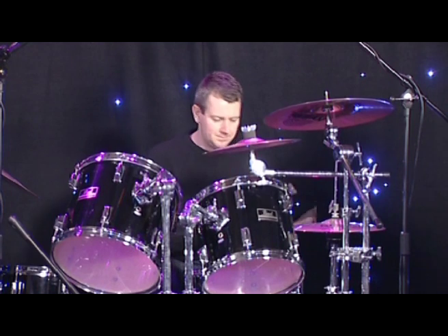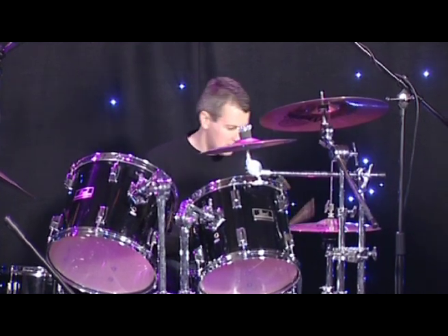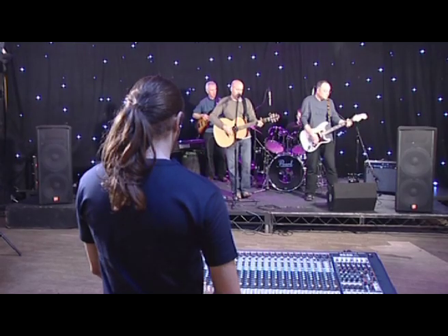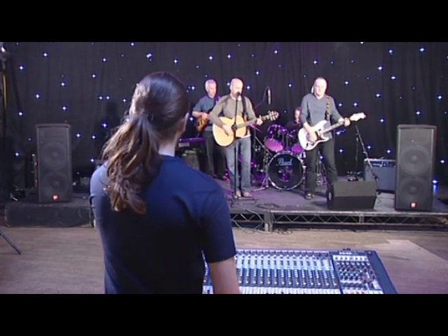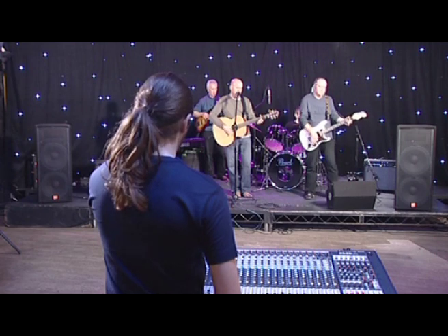Don't put vocal microphones directly in front of the drum kit or a guitar amplifier. Make sure nothing gets in between the loudspeakers and the audience. Aim them down towards the listeners, don't point them at the walls.